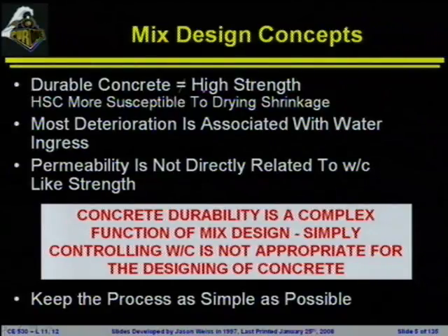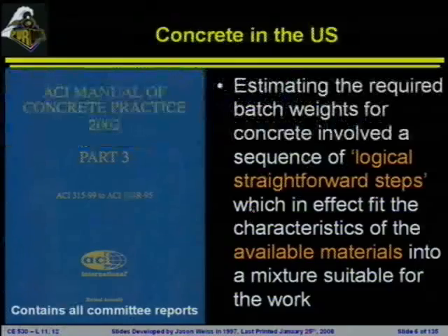So if you want concrete that's resistant to freezing and thawing, you have to put in a specification that is freeze-thaw dependent. If you want a concrete that's not going to undergo ASR problems, the solution is not to specify high strength. Strength is not a direct surrogate for durability, and we'll keep coming back to this. As we've mentioned before, most deterioration is related to water flowing through the material, or water freezing inside of the material. This is a complex process, and we want to try to keep the process as simple as possible.